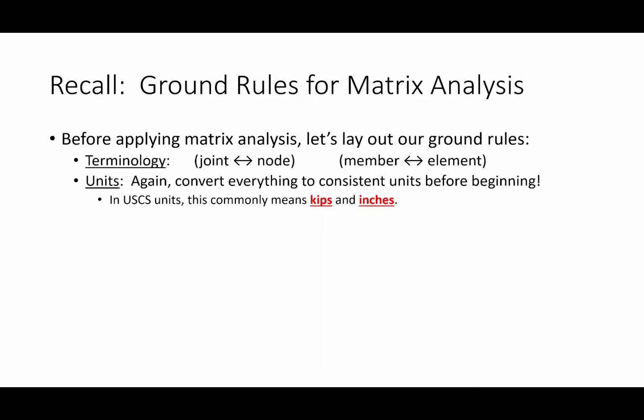Units. Everything I'm about to do is blind to units. Everything has to be in a consistent unit system. We will typically perform our analyses in kips and inches, so whenever you look at a problem, you had better convert right off the bat. Now what about sign convention? This is really important. We need to refer to all of our quantities consistently.